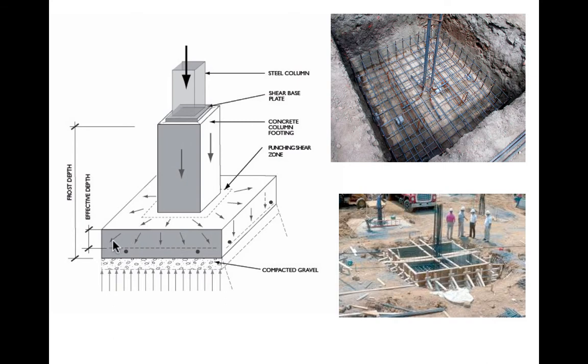That spread footing is going to have reinforcement in it because it's going to take a lot of shear, a lot of bending. And it may be that right around the column, we need to either make the spread footing a little bit deeper to handle this extra shear, or make the column a little bit wider, right? Bell the column out, add some geometry in here that's going to, again, maximize the interface between the column perimeter and the footing section. Underneath it, usually we'll have a layer of compacted gravel, again, to keep water away from the foundation, but also to ensure that we have a very broad bearing base below.